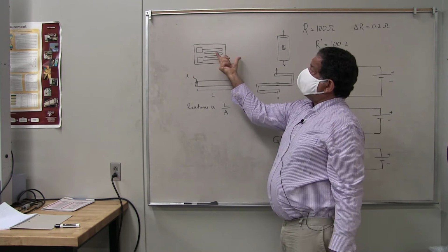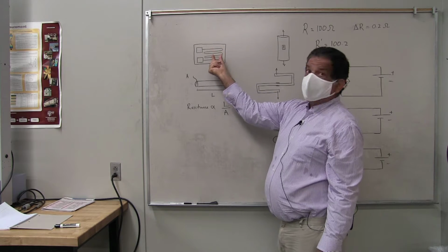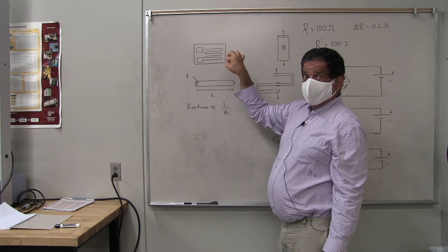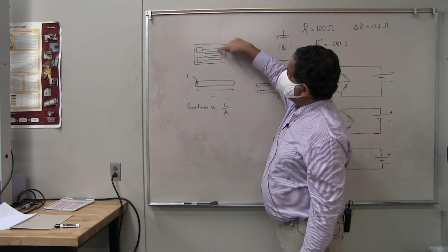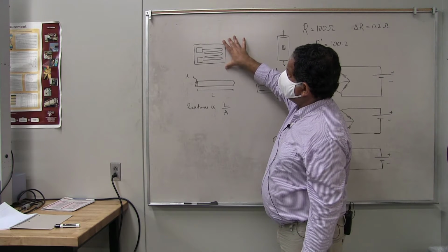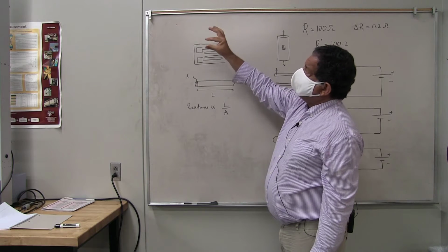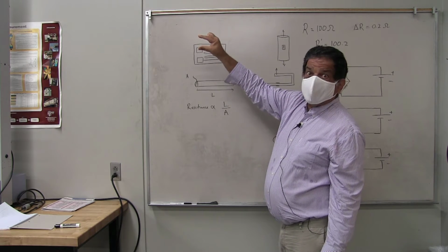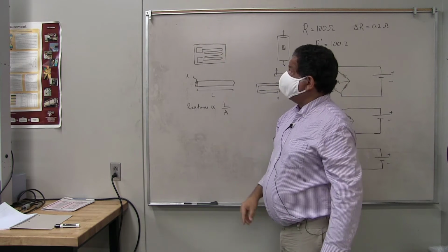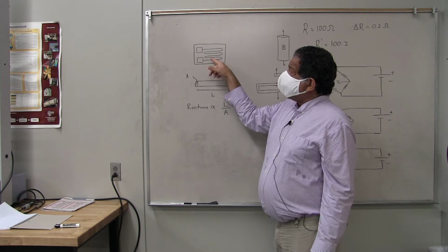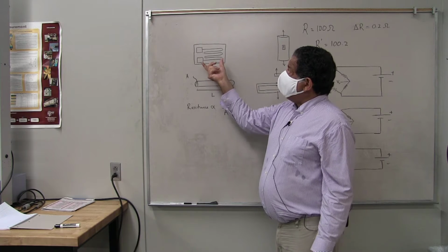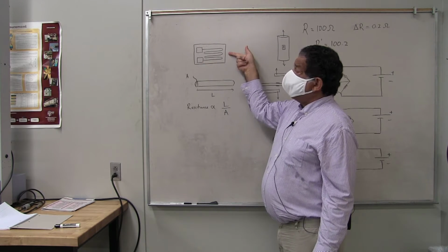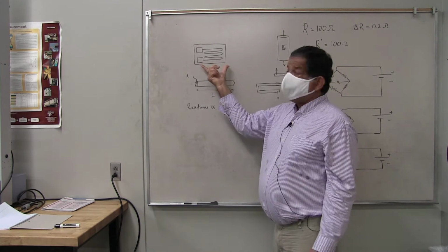Because if I stretch it this way, then all of those little wire segments are getting longer and thinner. But it's quite insensitive to deformations in this direction, because if I stretch it this way, all that happens is essentially the loop opens up like this, which is a very small effect on the resistance. So this is a highly specific device as far as the directionality goes for measuring the deformation of the underlying